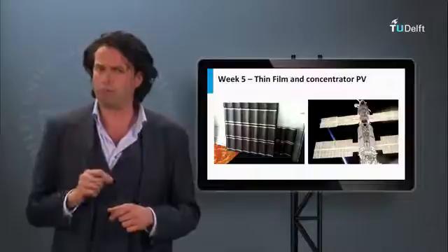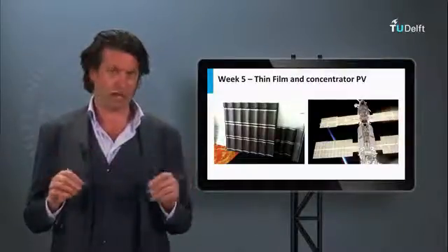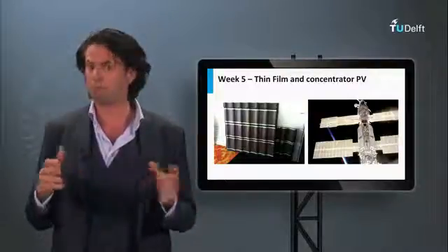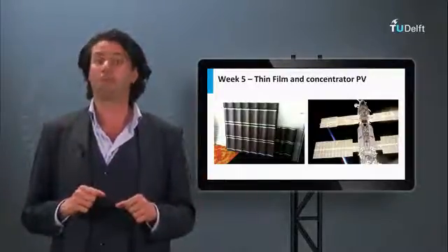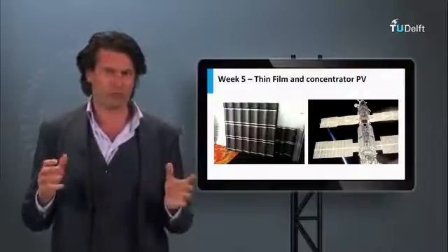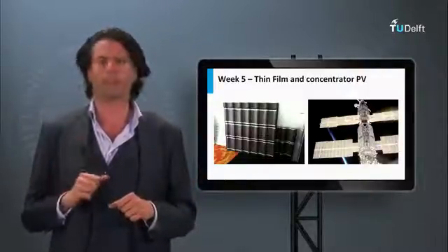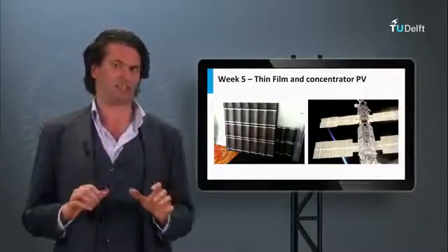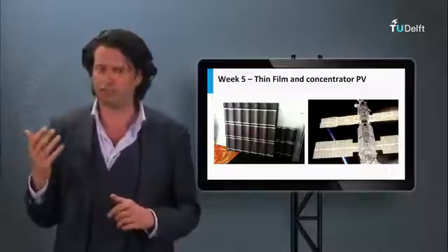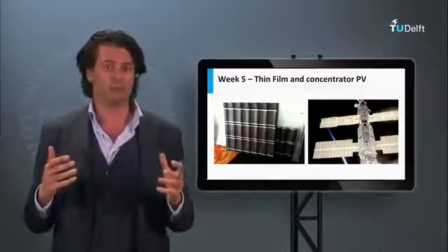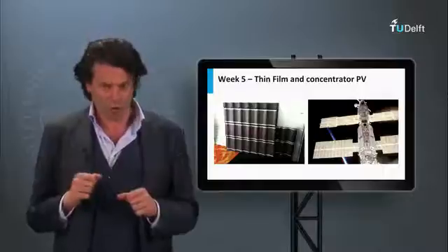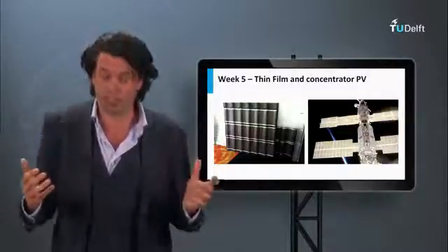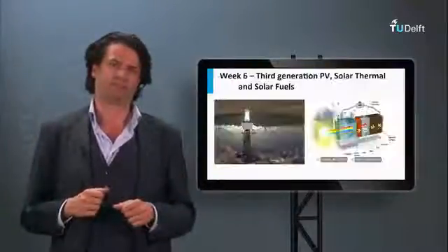We have quickly touched upon the various other PV technologies, like III-V semiconductor multi-junctions, the cadmium telluride PV technology, the CIGS PV technology, the thin film silicon technology, and the organic-based PV technologies. Every PV technology has its own advantages, such as the high conversion efficiencies, abundantly available source materials, low cost price per watt peak, the possibility to process it on flexible substrate, etc., etc.